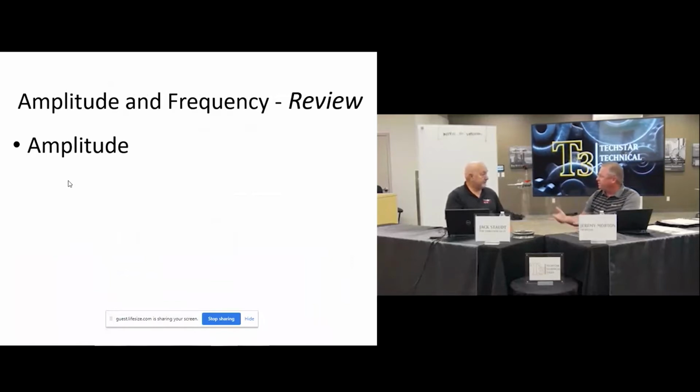Yeah. So if it's an orifice plate, you're getting a lot of noise from that, or maybe piping or something, or wires flapping in the wind, compared to a displacement or proximity probe that's actually mounted to the bearing and looking at the rotor itself. Those are much less susceptible to outside noise influences like that. That's correct. Yeah, case mounting, you could pick up anything.